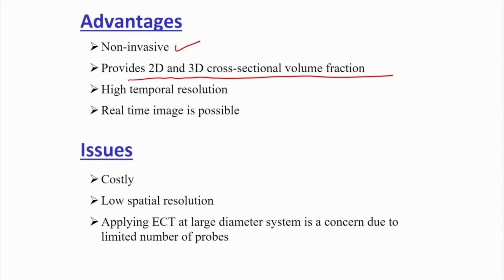Temporal resolution is very high, you are using electric currents based on the current signal. Temporal resolution is very high, up to 10 kilohertz you can go. And real time imaging, this is the major boost, that you can have real time imaging. You can see what is happening inside. So, suppose you want to see how the two phases are mixing with each other, say it is a liquid system, you want to find how they are mixing. I think this is the technique we should use to find that mixing, the way I have showed you how the dye is mixing. So, that is the major advantage.